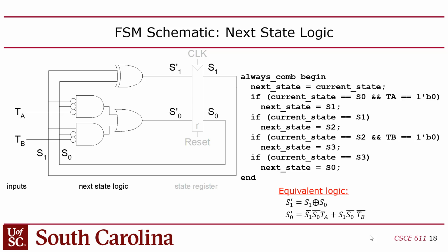In this case, I broke my own rule. I think I told you guys that I prefer to use assign statements for combinational logic. But in this case, I'm using an always_comb with an if statement. You could use a case statement in here too, since it's an always, or like I said, you could use an assign statement here. But this is purely combinational logic. So it's just essentially some way of taking the current state and the inputs and setting the next state. There's many ways you can do that, however you want to build your next state behavior, right?